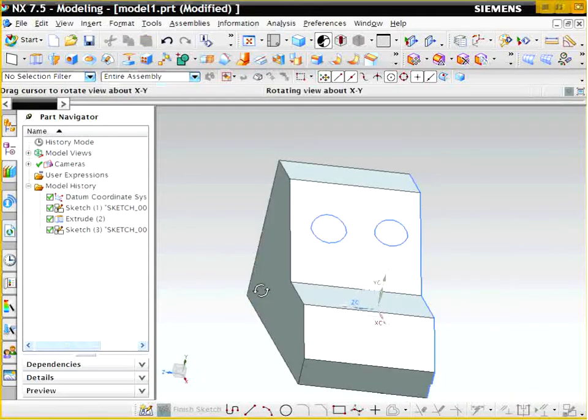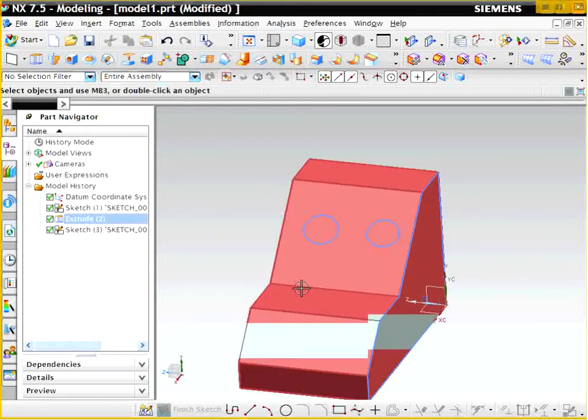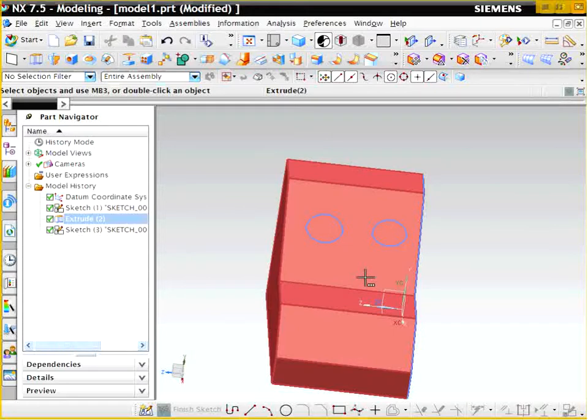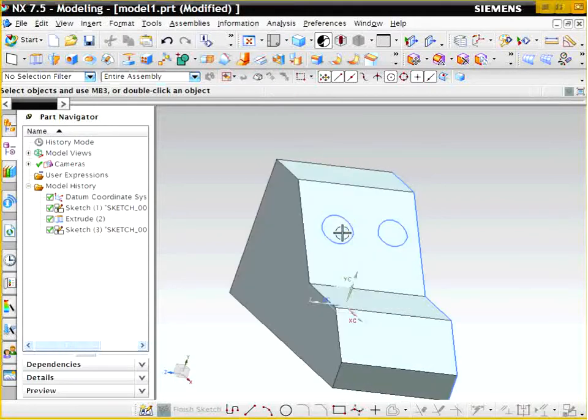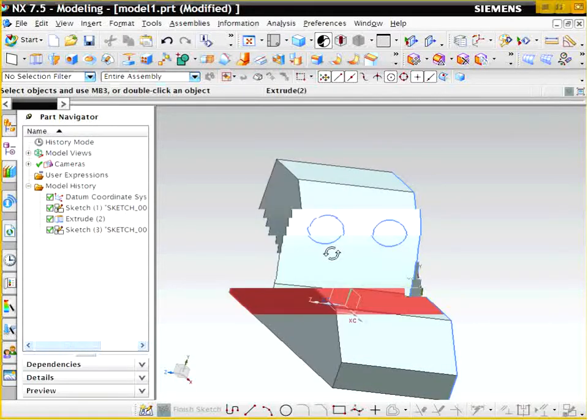What you see is that I drew these first two sketches, and those sketches appeared on that particular plane. When I clicked Finish Sketch, the other 2 drawings that I drew disappeared. The reason that happened is that all of those drawings were done on the surface of this plane. So you see they're all on different surfaces.